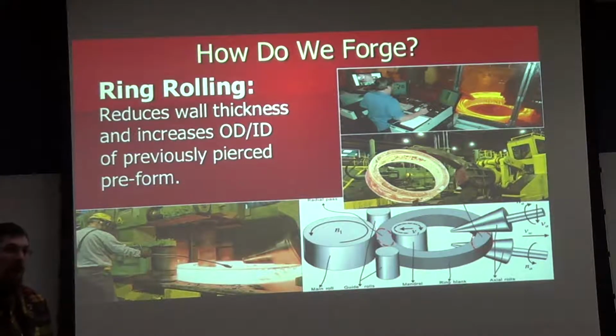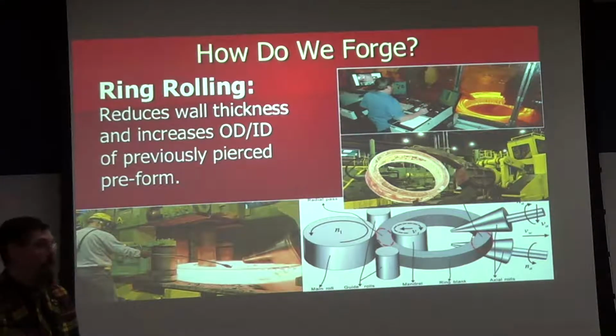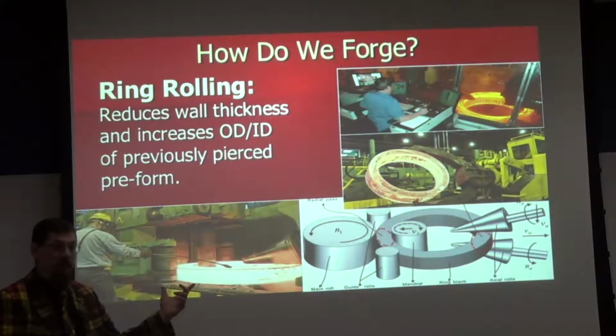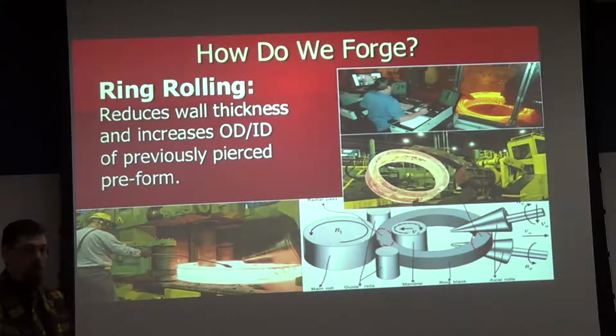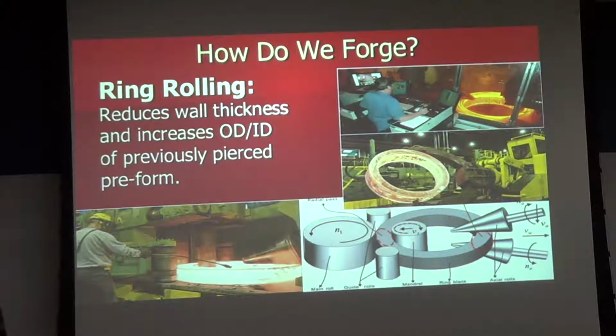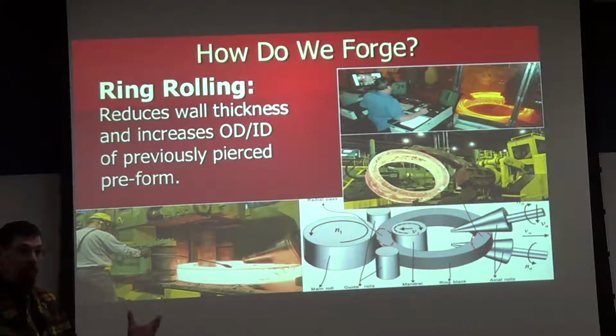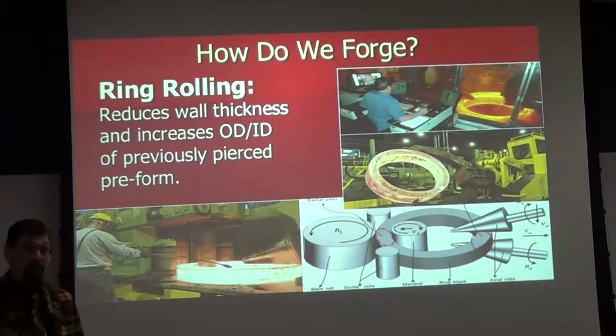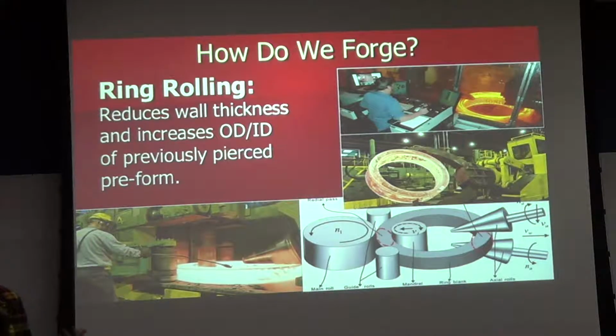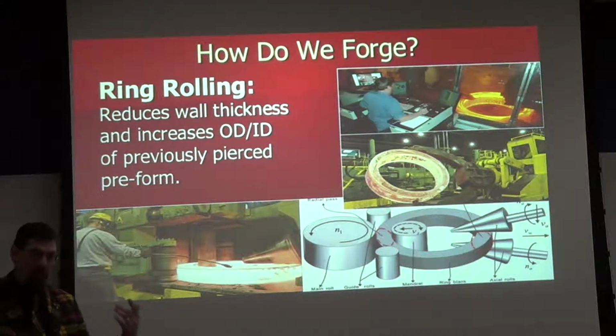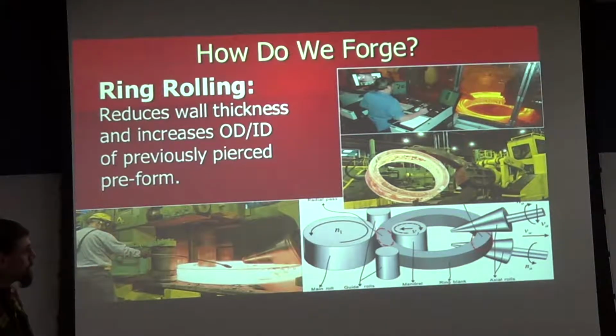That is the primary reason for making a ring by this technique: you have uniformity of properties all the way around. So if I'm going to make this ring eventually into, say, some sort of a gear, for example, where there's going to be high load on the gear teeth, there's going to be wear on those teeth, I want the confidence that I'm going to have uniformity of performance all the way around the ring.